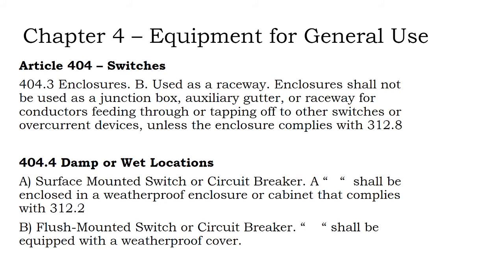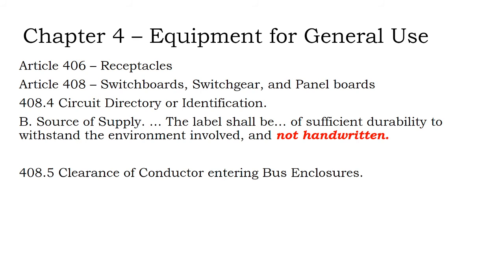And we talk about some nuances of weather exposure. The main thing with weather is that there's weather rated devices, fittings, couplings. You know, you can have EMT conduit with an EMT connector, but there's also a rain tight EMT connector. And most of the time, EMT is not used in outdoor construction work. You're dealing with more robust, rigid conduit, concrete encased raceways, more weatherproof, weather-tight things. And so these specialty pieces like rain-tight EMT couplings, you don't find at Lowe's or Home Depot. You have to get them at an electrical supply store.